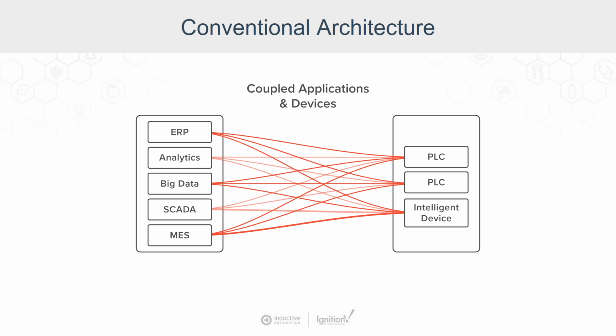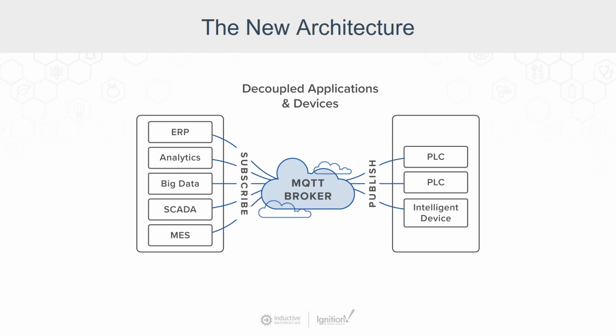And so from an architectural standpoint, this is really not the best way to go about it. As I mentioned earlier, we want to be able to connect devices to infrastructure. And the way we do that is to have devices publishing data to message-oriented middleware, such as MQTT. We're going to be talking a lot more about that here today. That is an open protocol that is a publish-subscribe methodology where we can have the PLC sensors and the data publishing its information to an MQTT server, the middleware there, that then there can be many consumers of the data who can subscribe and get access to it.